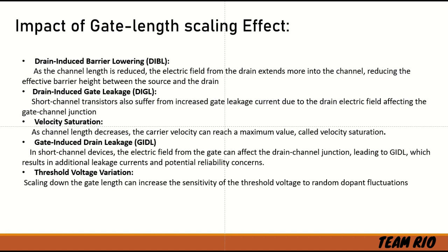Drain induced gate leakage. Short channel transistors also suffer from increased gate leakage current due to the drain electric field affecting the gate channel junction. This is also known as DIGL and leads to a higher off state current, which can significantly impact the overall power consumption of the device.